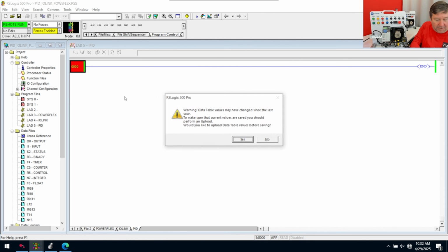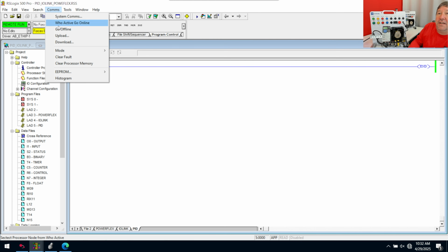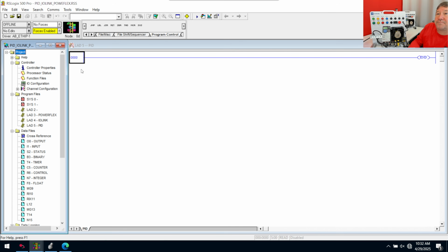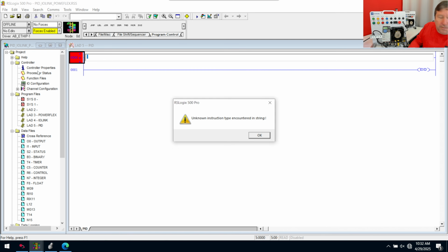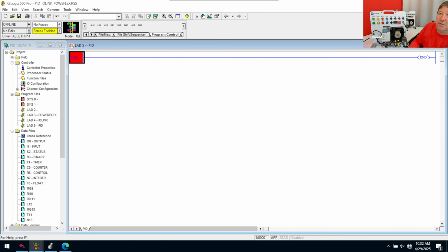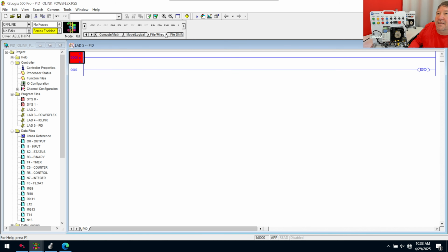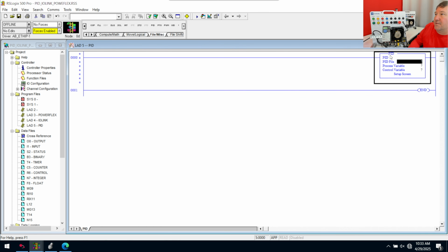So first of all, I'm going to go ahead and save what we have. And then we're going to go to communications, go offline. And let's go ahead and bring down a new rung. And the first thing we're going to need is a new rung. Now we can go through all these tabs here, but also you can just right click and we can insert a rung. And then we're going to go to the file miscellaneous and bring down a PID instruction.